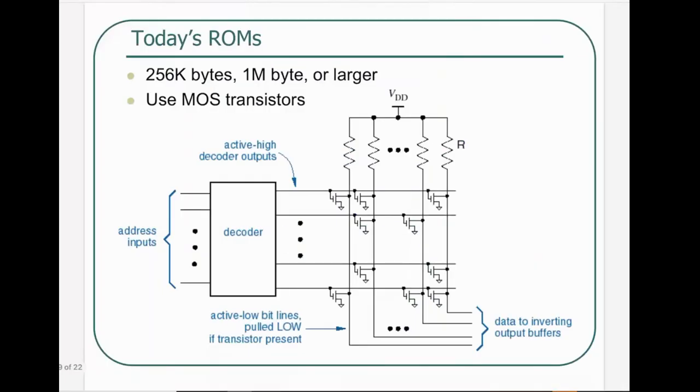Now, we were talking about RAM and ROM. We spent some time talking about static RAM: how each static RAM cell is constructed using transistors. We looked at a 6 transistor configuration inside a static RAM cell to store 1 bit of information. We also looked at a highly dense alternative in dynamic RAM, in which we could do the same job but with 1 transistor and a capacitor. The capacitor is getting charged and discharged, and you're using the transistor to give access to that capacitor voltage.